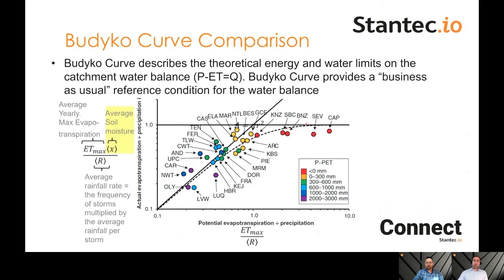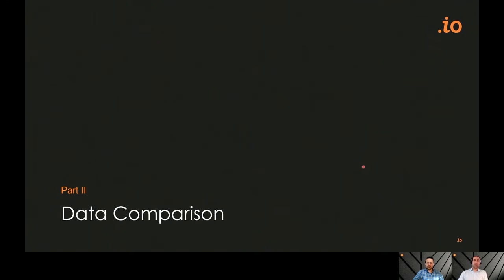So we have lots of evapotranspiration, and that corresponds to between the dashed line here and the solid line here having much less runoff. And as you get drier and drier, pretty much everything just gets exported to the atmosphere through evapotranspiration. So we can calibrate to this, and we get pretty reasonable results as I will show with this data comparison.